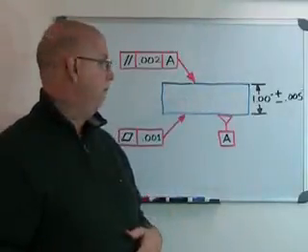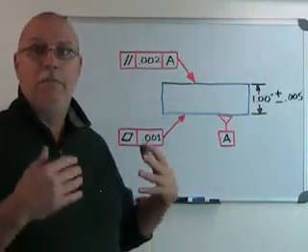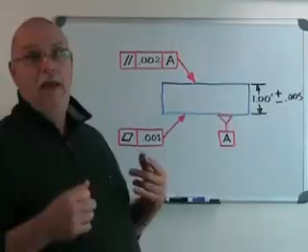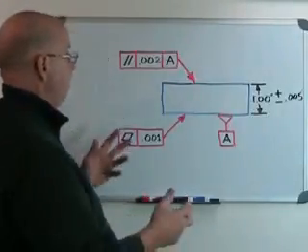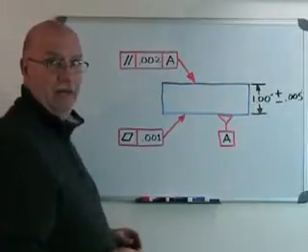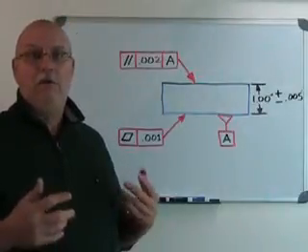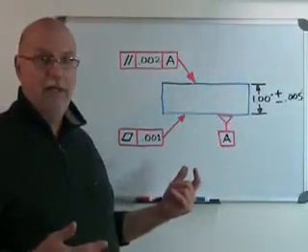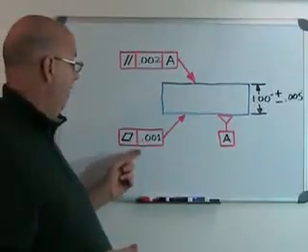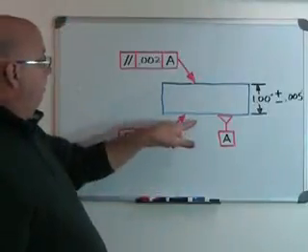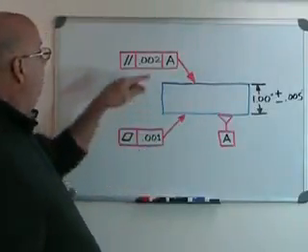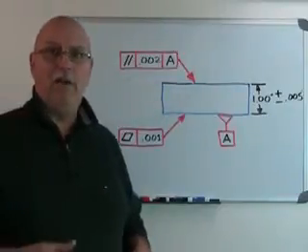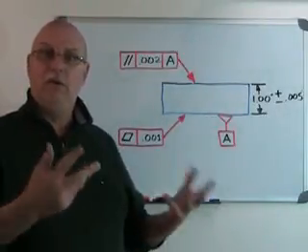That's not terribly accurate, but I do want the part to be parallel, and for that I need two things. I need flatness and I need parallelism. So here I have flatness to within 1/1000ths of an inch, and the part is flat to itself. A flatness does not refer to another part of the piece that we're looking at. It's just flat, okay? So flat within 1/1000th of an inch for this surface here indicated by the arrow, and parallel to 2/1000ths of an inch for this surface, but parallel is related. Related to what? To another surface.